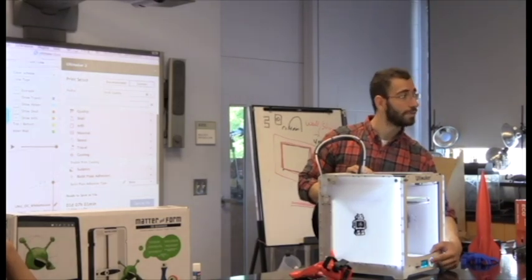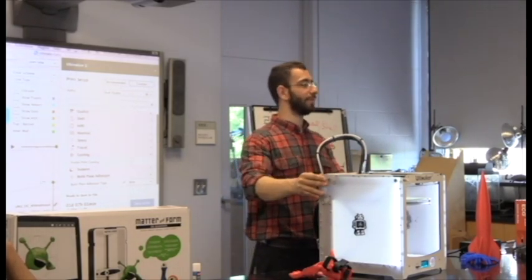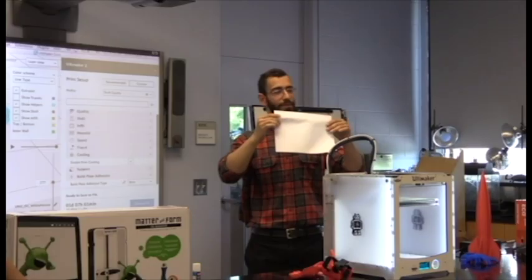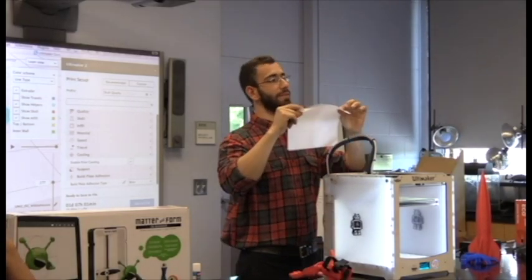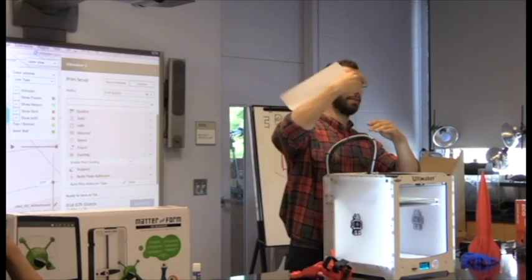As you move this up and down, it brings the whole thing up and down, so the whole plate first goes up. What you need to calibrate this is a very, very expensive piece of equipment. The thickness of a piece of paper is the space that you need between the bed and the nozzle.